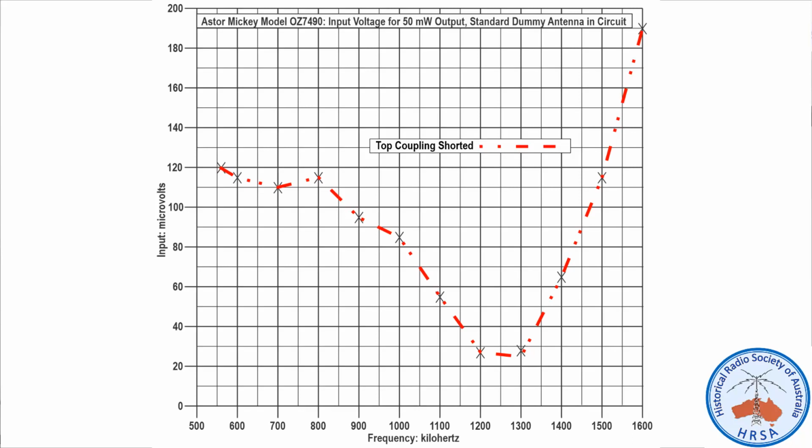That's a 10-to-1 difference between mid-band and the top end, and a lot of sets actually get more sensitive as you get towards the top end, right? So what's going on there? And as well, the low sensitivity was about 1/6 of what it should be, so it's obviously something really wrong in the circuit.